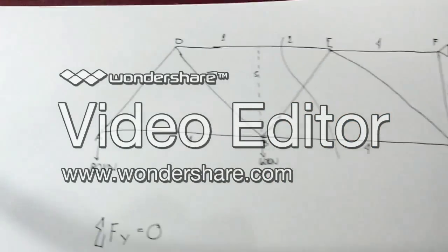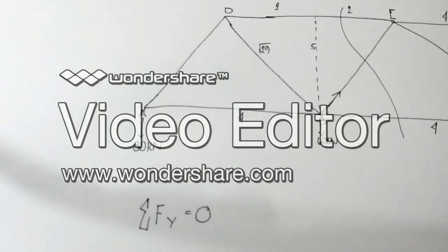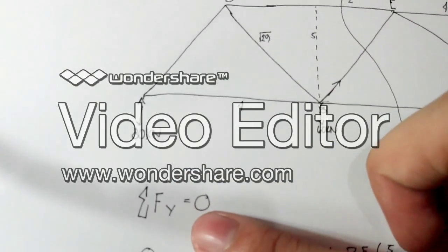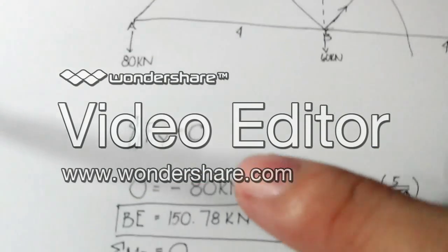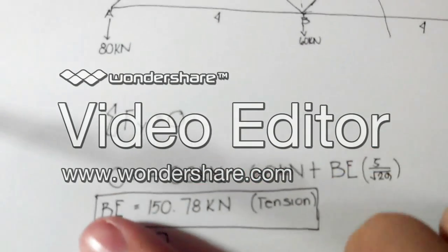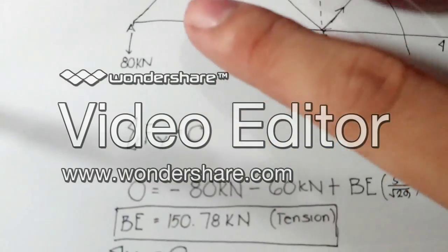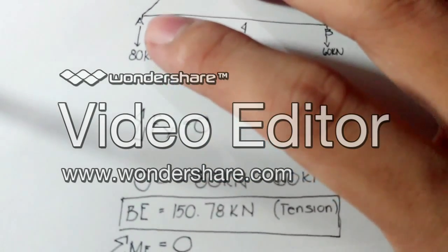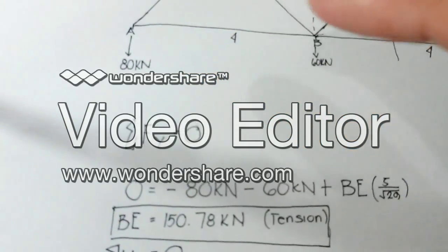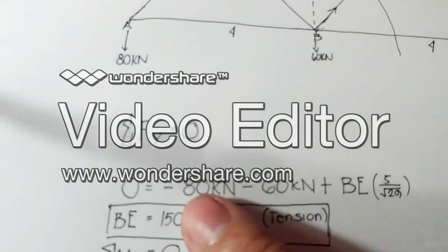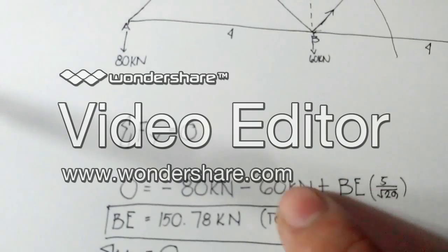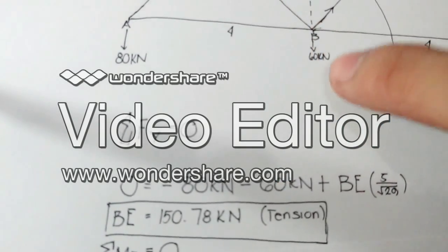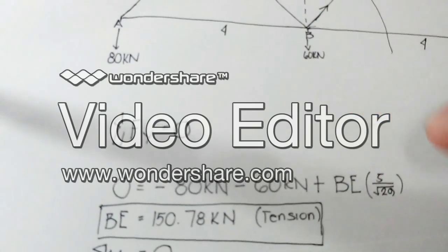So there you go. Summation of forces along the y-axis is equal to 0. So 0 is equal to negative 80 kilonewtons. It is negative because it is going downward. So negative 80 kilonewtons, negative 60 kilonewtons, which is here in B, and the BE.